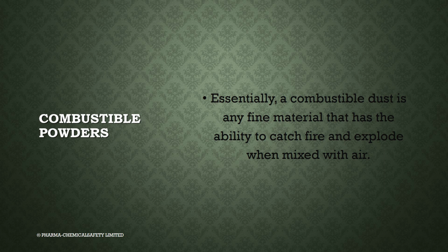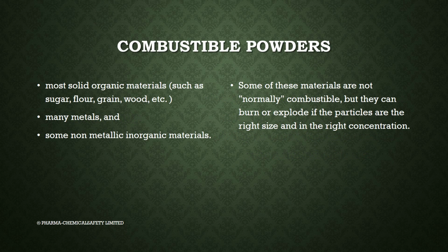The very basic definition of combustible powders is: combustible dust is any fine material that has an ability to catch fire and explode when it's mixed with air. That's when these types of materials become so dangerous, and that is the essential definition. These combustible powders could be any solid organic material such as sugar, flour, grain, wood, cinnamon, many metals such as zinc, aluminum, and some non-metallic inorganic materials.